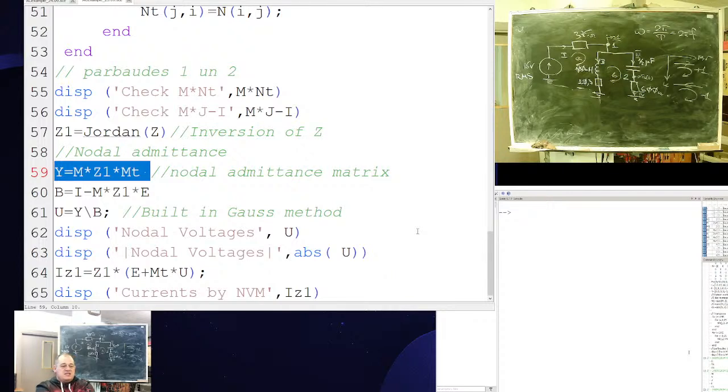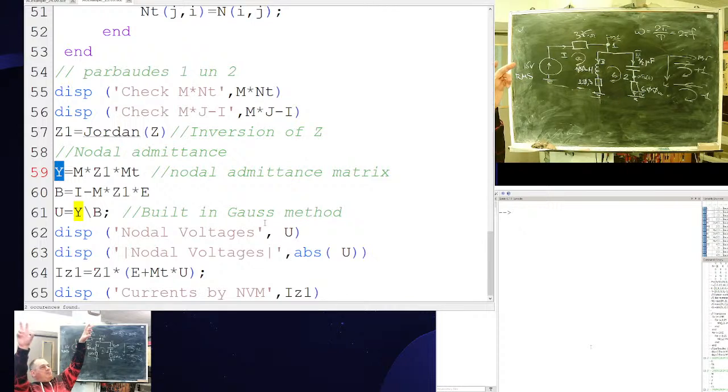We do it as in a DC network. Nodal admittance was M multiplied by the inversion of the resistance matrix and multiplied by M transposed. Here, the nodal admittance matrix actually has its structure GA, B, minus B, GA. What's GA? Real part of. See, if resistance has a complex part, conductance or admittance will also have a complex part.